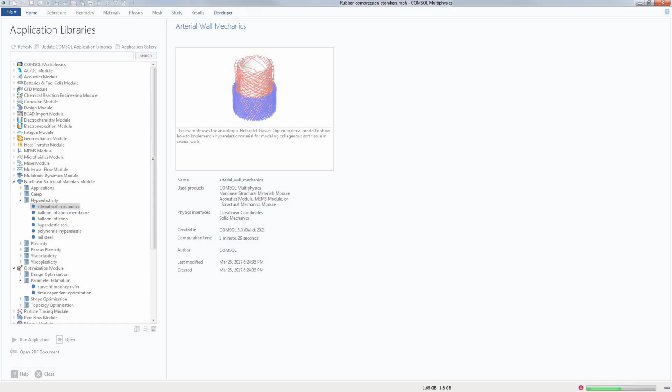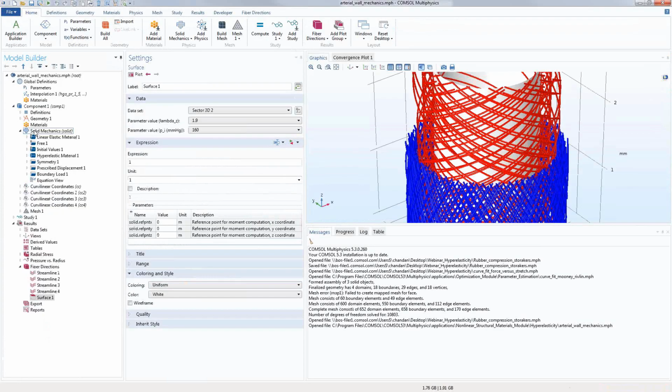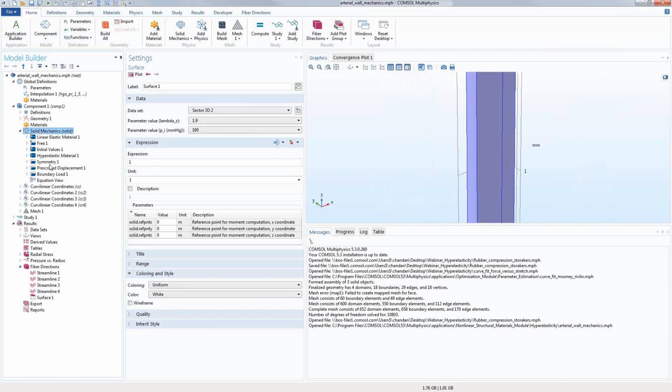While that opens, let me see a few other questions. One more question here from Douglas: can you add in vibration from an acoustic source? Yes, you can model vibration from an acoustic source easily. That is what we would call acoustic structure interaction. In fact, in some of these microphone models where the membranes could be hyperelastic, you may need to account for hyperelasticity. So definitely, and that would be part of the Acoustics Module in COMSOL, where there's a specific interface called acoustic structure interaction that will allow you to model hyperelastic materials along with acoustics.